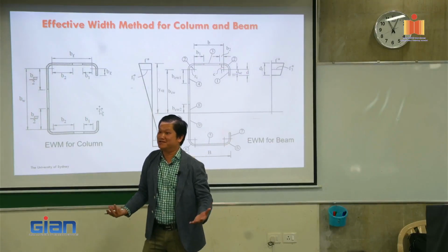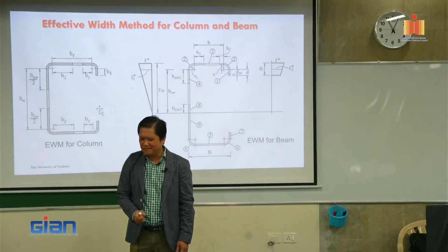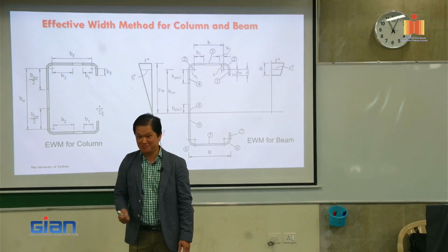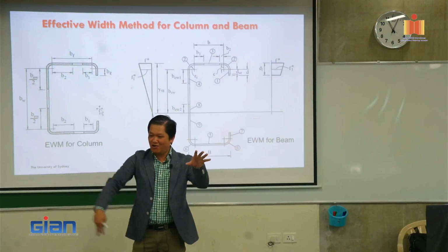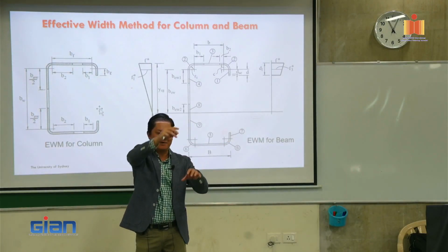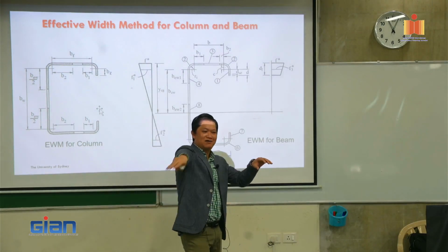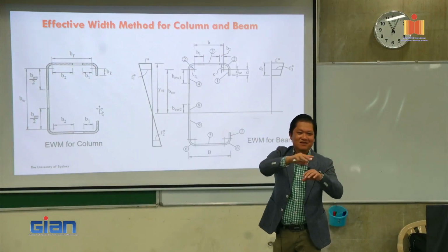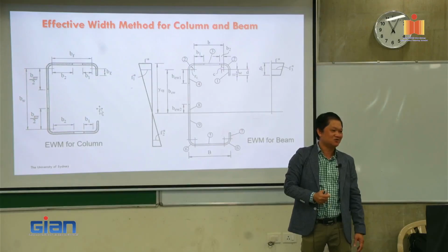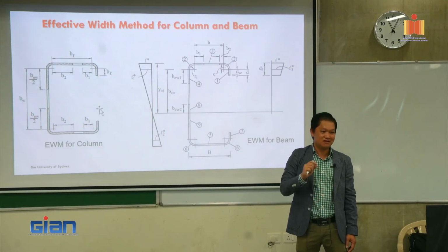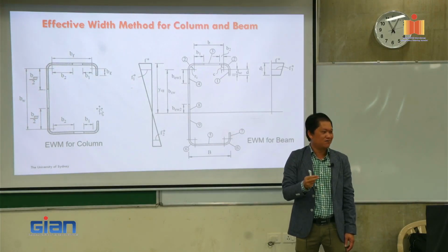Then what you have to do is try and error. You have to assume that it's there, and then do all the calculation and come back. It's slightly different, and then you adjust a little bit and do another one. So if we're lucky, we can do a couple of loop iterations. But if not, then you're going to spend pages until you get the correct position of the neutral axis.